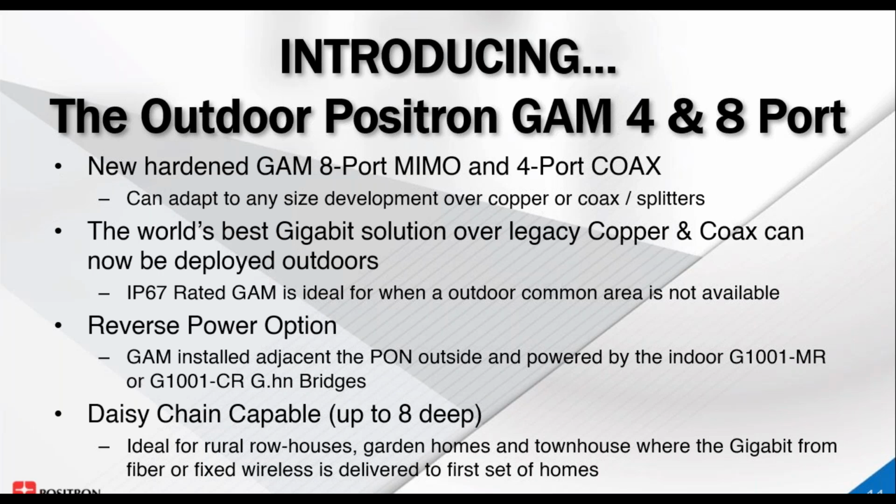There are 2 roles in G.hn. One is a domain master. That's usually the GAM, and the G1001 is an endpoint device. But through a configuration setting, we can take a port of the GAM or multiple ports and turn them into endpoint devices so they can connect to another GAM device and create a chain of devices. And we can go up to 8 deep. So we'll cover that in a few more details coming up.